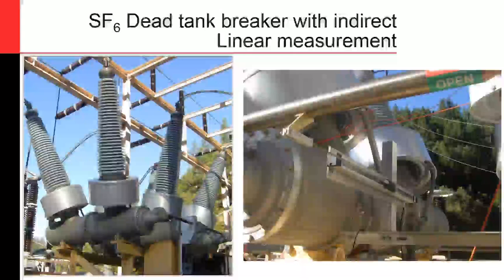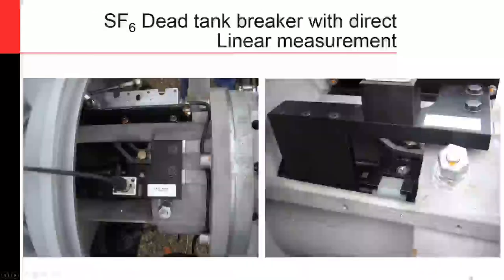parallel to the interrupter. So even though this is an indirect connection, that little clevis is designed so whatever that interrupter moves in the circuit breaker, your transducer is going to move and mimic it, so it's also a one-to-one ratio there. So you're getting the exact stroke and the exact velocities and everything of that interrupter.